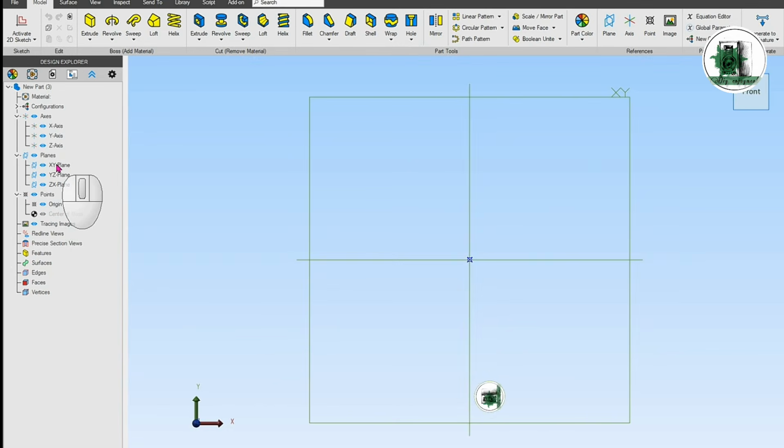In part 2, we'll model the horn in CAD. First, we'll create the speaker driver. You can use software like Fusion 360, SolidWorks, or Alibre Design. I personally use Alibre because it's lightweight and fast. A 2D sketch is the key to getting the final 3D shape. Select the XY plane and click on Activate 2D Sketch.